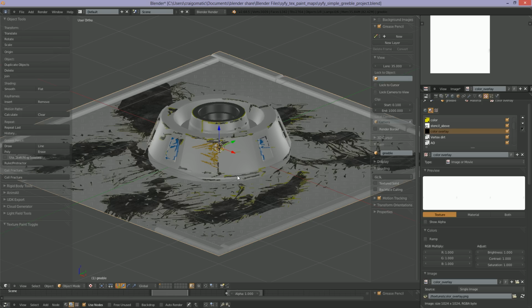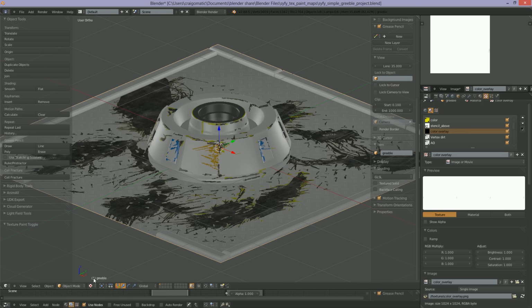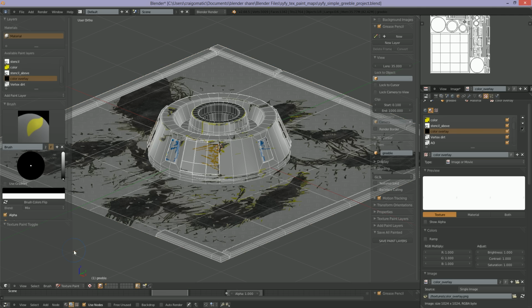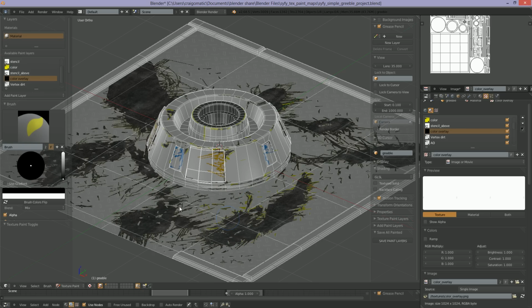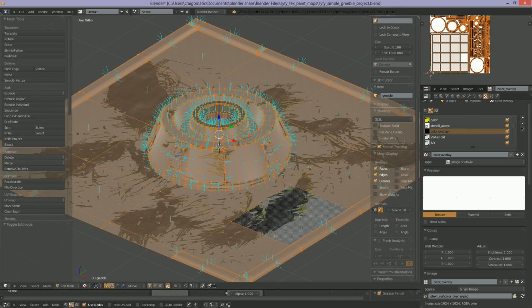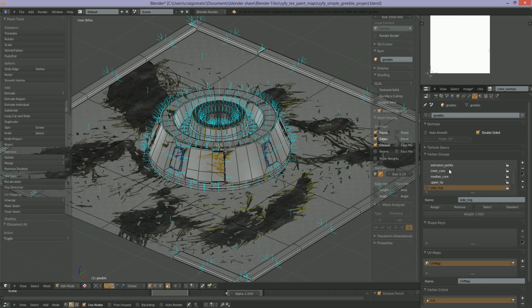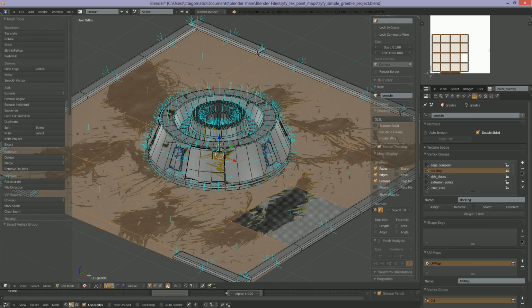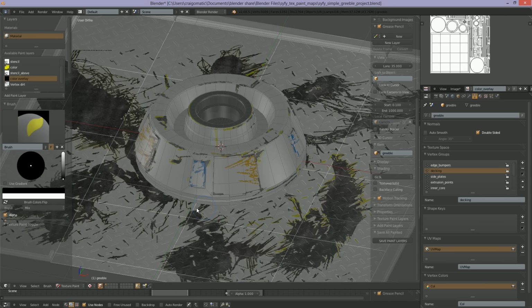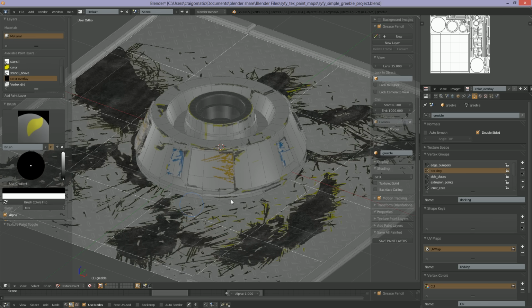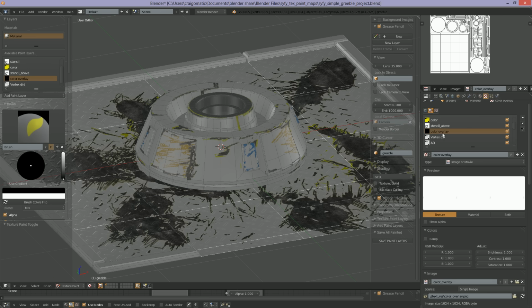What I wanted to show you is how to make brushes to work with in texture paint. Here I've got everything turned on. I'm going to just work with the decking for now, so go back to edit mode, A to deselect, and as we did before, I'm going to find the vert group for just the decking, select that, and go back to texture paint, and like I said before, with this icon here for face masking, you'll see the highlighted selection area on just the plating, and that should enable us to paint on the color overlay.